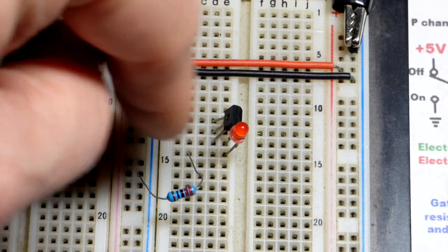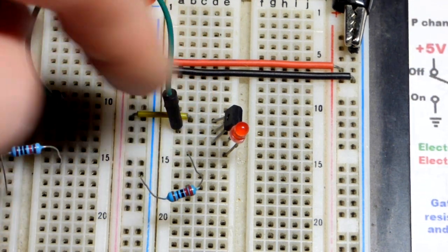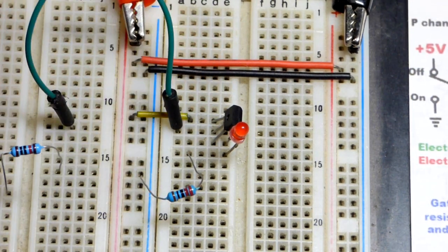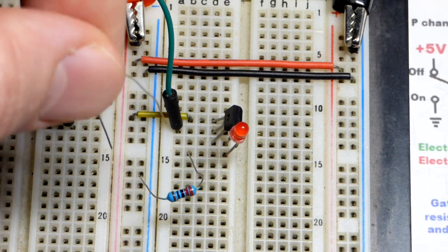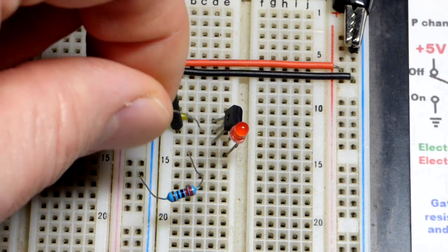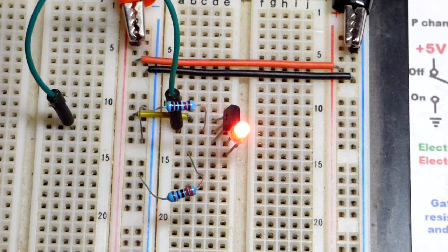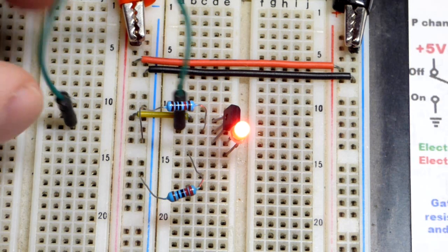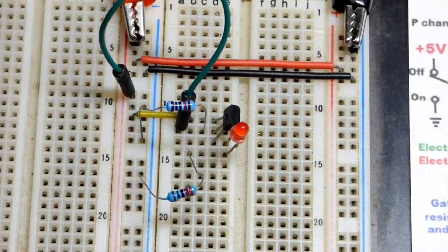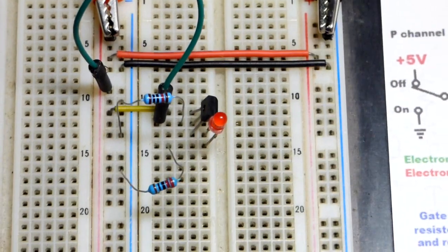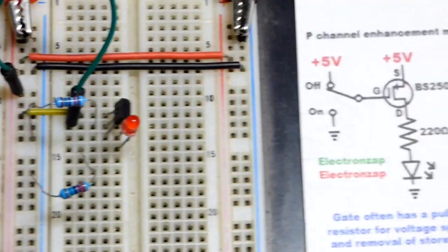Of course, always look at the data sheet. Definitely look at it for all the specifications and everything. But also the pin layout. I may make a mistake on my drawings. The data sheet is always the best source for getting information on the components that you can get. So now we got our pull down, but if we want to get it off, positive supply. That's the basic rules of using the P-channel enhancement mode MOSFET as a switch.